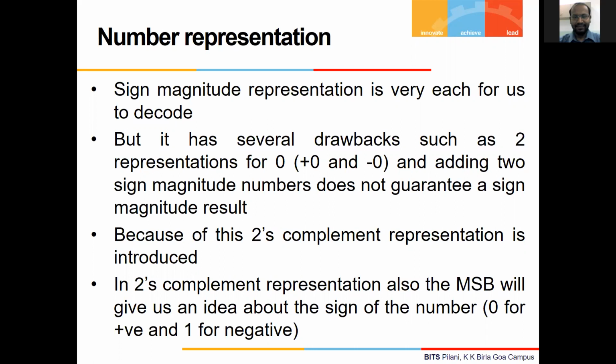Now in hardware, when you test the actual software implementation, whether you use normalized input or not normalized input, proper output will come. But in case of hardware, if I use everything normalized, then my input bit width will also be based on this assumption. Input is normalized. That means in hardware, I may require an additional block for normalizing it when I actually deploy it. If there are pixel values, I will have to normalize them before feeding.